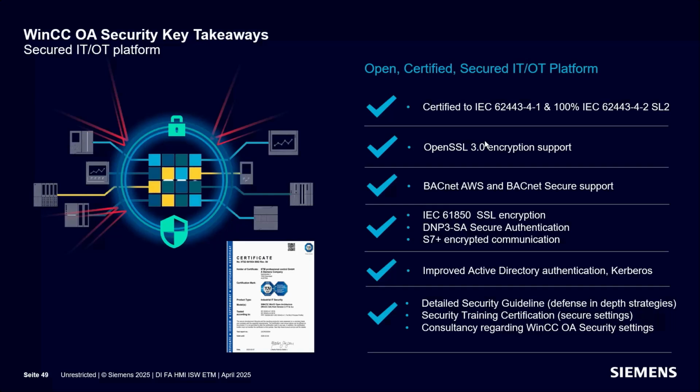All of that works with OpenSSL certificates, but also, of course, Kerberos. Kerberos is, of course, the go-to solution when you have a domain, like a Windows domain with a domain server. The Windows servers come with Kerberos, and all our managers speak Kerberos natively. So that is the easiest thing to have the Active Directory synchronized in WinCC OA and use Kerberos for the highest security standard.